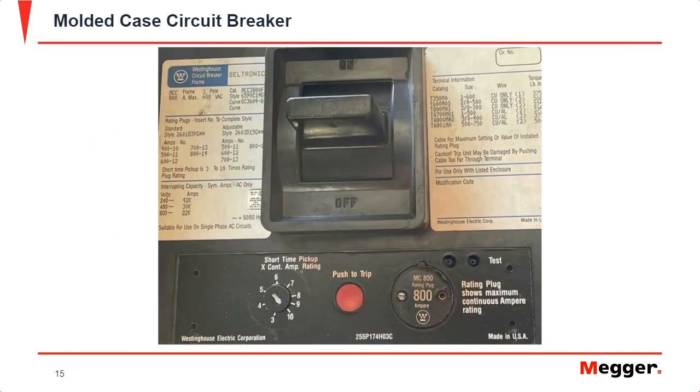Here we have another look at a larger molded case circuit breaker where you can see the trip unit as well as a rating plug inside it. So again, that rating plug is making it act like an 800 amp breaker. It's still the same as what it's rated for, 800 amp frame size. And you'll see this one has short time pickup on it. It doesn't have any other settings that you can adjust. Typically most breakers will always have a long time and an instantaneous setting that you would test, but on this one, the only adjustable one is going to be the short time.